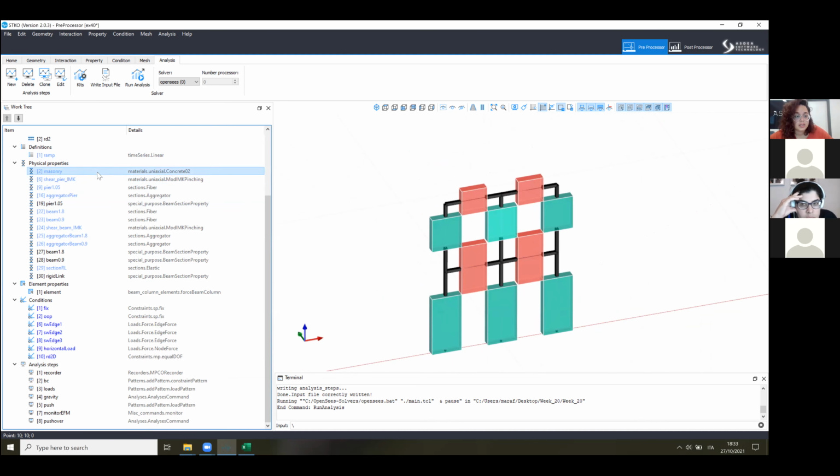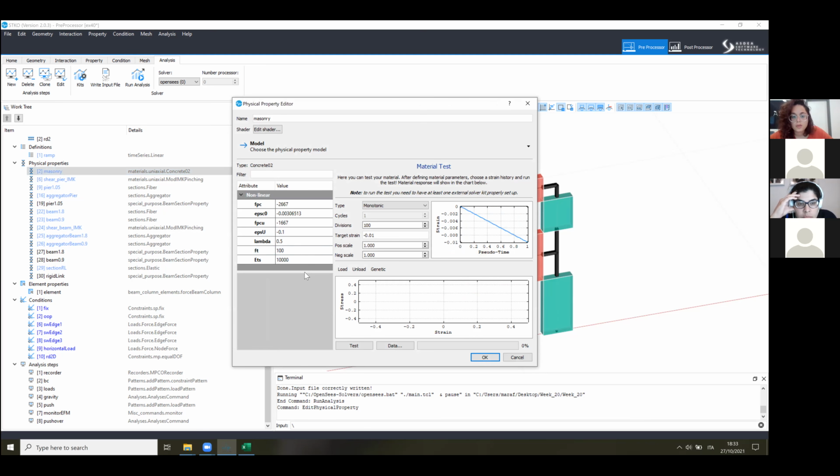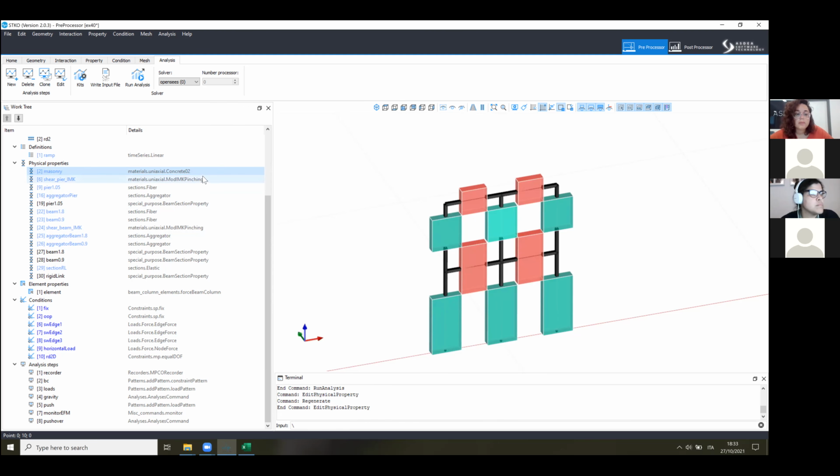And this is something that you can use concrete material, uniaxial material, hysteretic material with pinching for how you want your masonry to behave. And just for you to remember, I repeat again what I said at the beginning, because we don't have a slide for it today, and so you will not have a record of this.